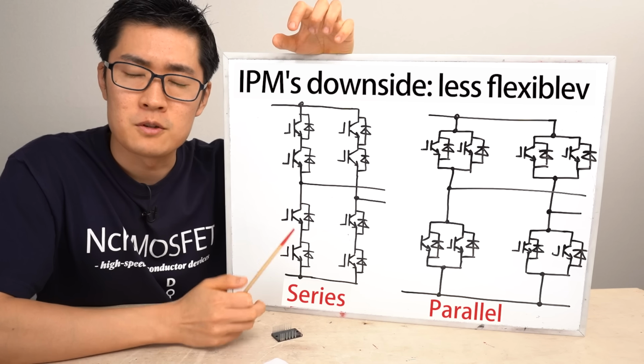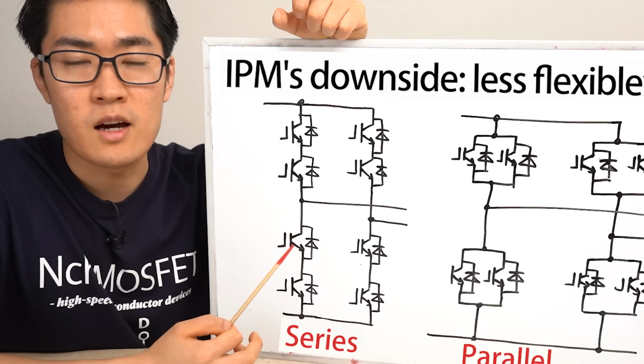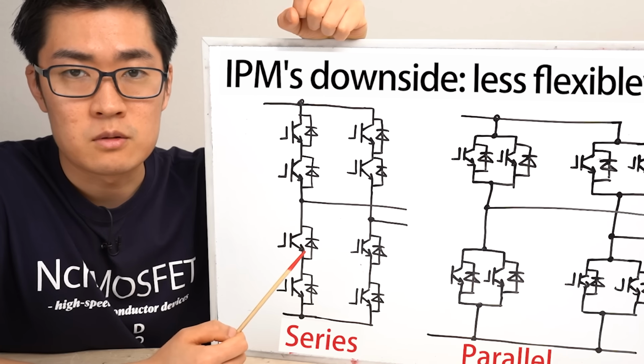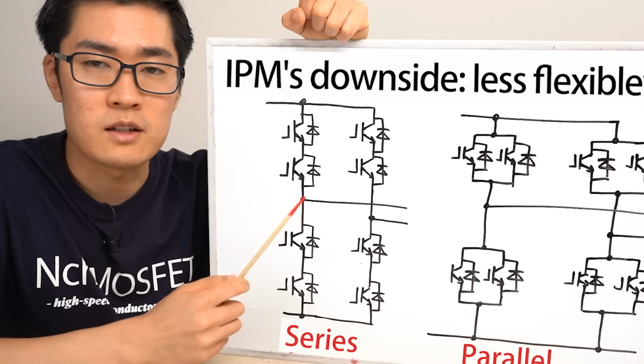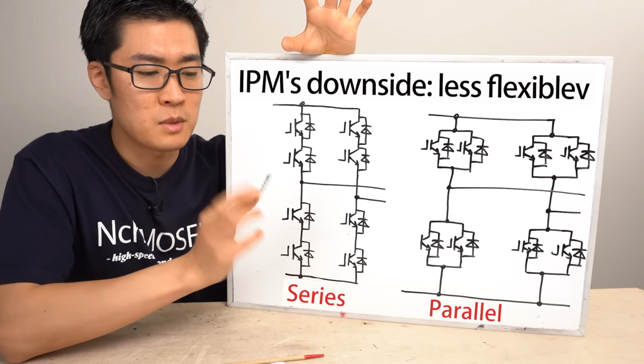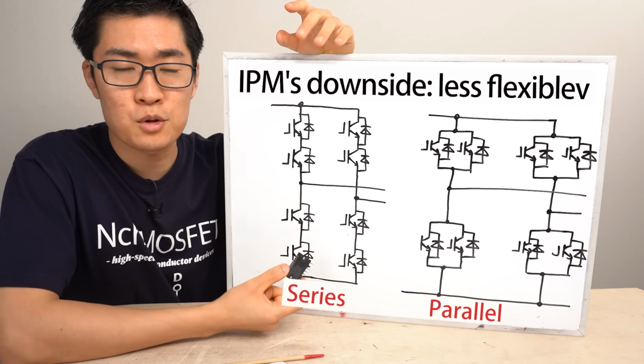Also, it is generally not possible to change the characteristics of the drive circuit inside an IPM. Therefore, fine-tuning by adjusting the switching speed, which is possible with discrete power semiconductors or conventional power modules, is not possible with IPMs. Even though IPMs have these kinds of drawbacks, the benefits outweigh the disadvantages, which is why IPMs are still widely used in many applications today.